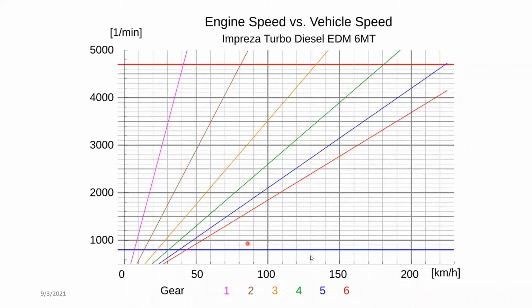So top speed can be achieved in 6th gear, right? But in 6th gear, the tractive effort it delivers is low. In first gear, it delivers higher tractive effort, so it can take more load. That's why when you increase the load in a vehicle, you have to come to first or second, a lower gear, right? Hope you got up to there.